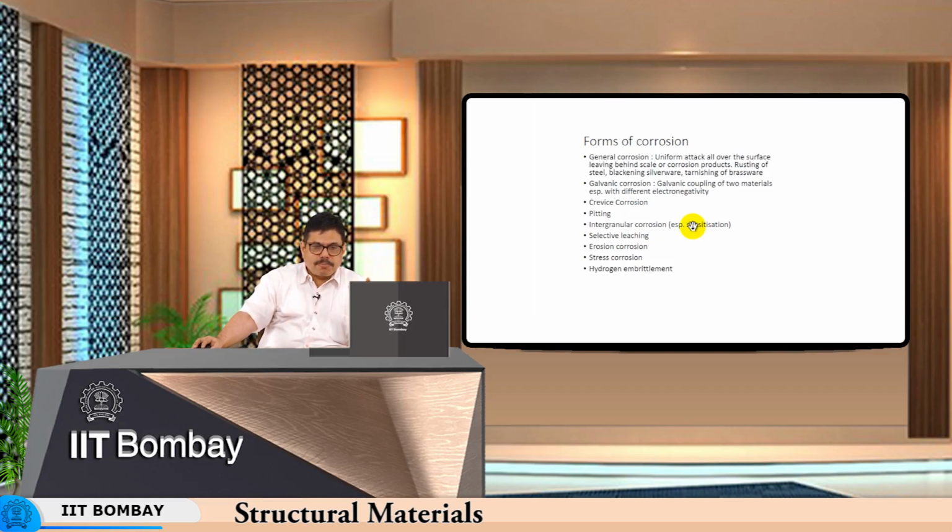These pits are formed at various points, and we will see the mechanism of this, but this is another form of corrosion where the material is eaten away at specific points, and the depth of that pit continues to increase with time. Crevice corrosion, on the other hand, is very similar to pitting, and so there are similarities between crevice corrosion and pitting, and this crevice corrosion also takes place over a period of time and gets deepened. More and more material gets eaten away